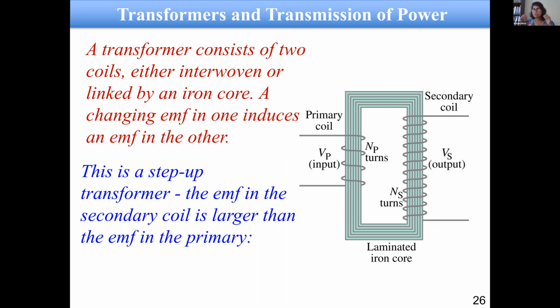That means you have one coil on one side and another coil on the other side. If I have a power plant on this side, and the secondary coil has many more turns, then your voltage on the secondary coil is going to be higher. So then you have high voltage, and then you come to the home. When you come to the home, we don't want 200,000 volts. What we need is a small voltage, right? So we reduce that voltage by doing exactly the opposite.